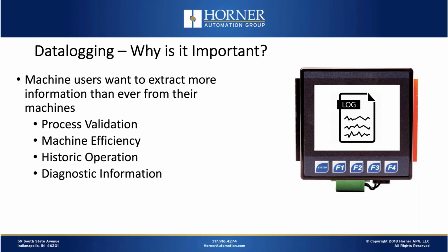And why is data logging important? Well, machine users more and more want to extract more information than ever from their machines. They don't just want to make parts. They need to validate the process that those parts were made in. They may need to measure machine efficiency, and having historical data can help them do that. They may want to look at the historic operation of the machine for diagnostics, yes, but also maybe for preventative maintenance purposes, for instance. So there's a lot of reasons why customers want to have data out of their machines, and data logging is a great way of getting that done.